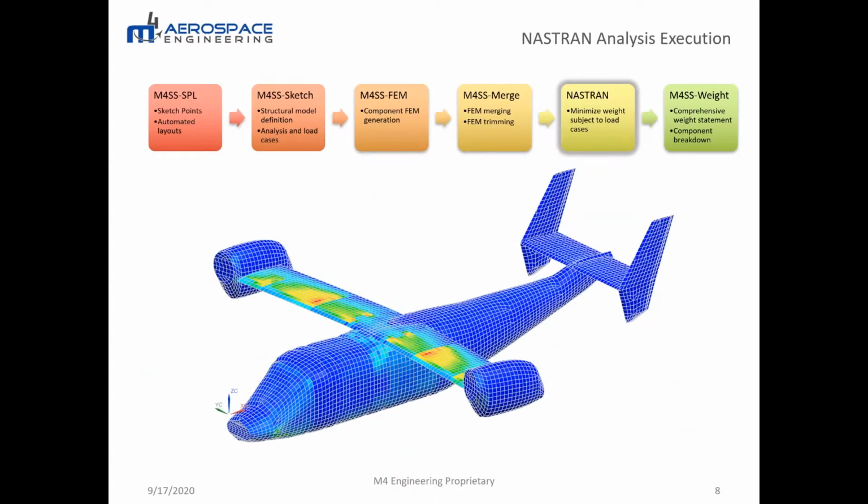And so moving on, once you have your FEM, it's important to note that this FEM is what we call optimization ready. So all of the analysis cards and details that are important to running an optimization routine are set up and constructed in a way that is ready for immediate execution within Nastran. And I'll point out just briefly that we support both NX Nastran and MSC Nastran versions. But once you get to this step, essentially you're ready to run your optimization and size your vehicle structure subject to the load cases that you're interested in considering.